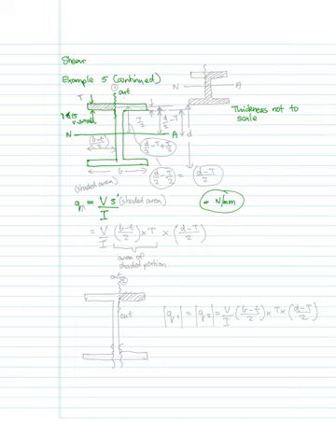So if we wanted to work out the shear flow, we would use the same equation as before, and we would just shade the bit that we want to calculate. We could, of course, shade the rest of the section instead, but that would be a more involved calculation, though you would get exactly the same answer.